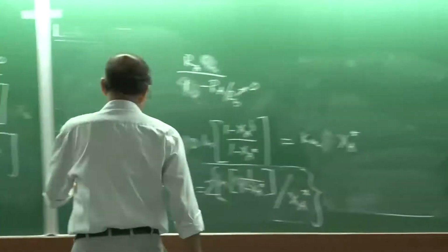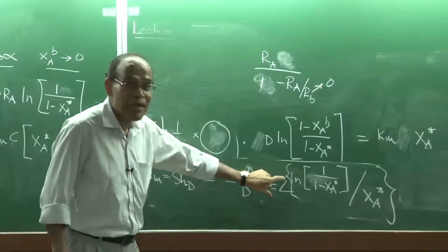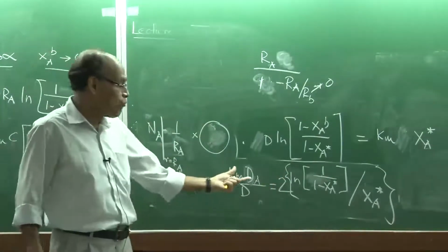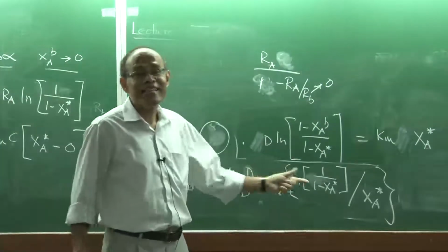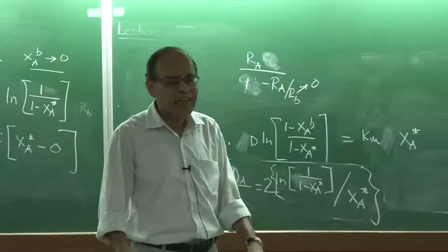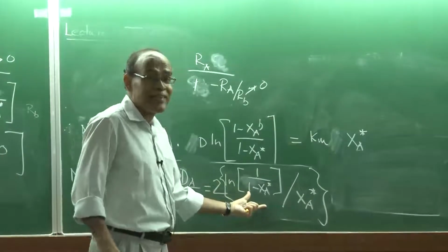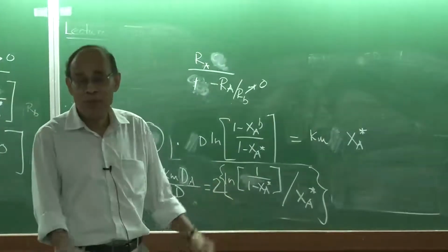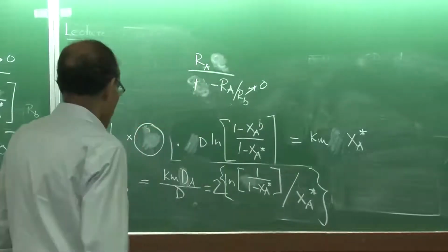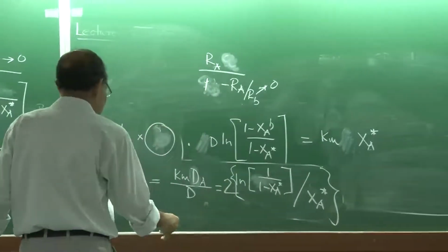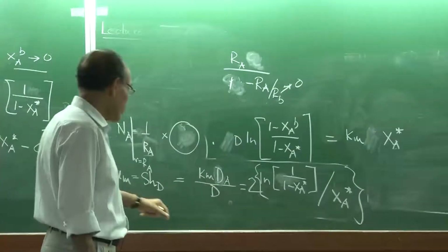So, this shows the characteristic feature of 2 for the spherical geometry, and it says that the limiting value will be 2. In this case we are not dealing with a direct forced convection scenario, but there is an amplification factor, which in the context of heat transfer I have explained, by adding the Reynolds number and Prandtl number component to the nominal or minimal value of 2.